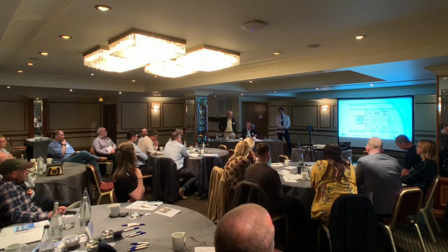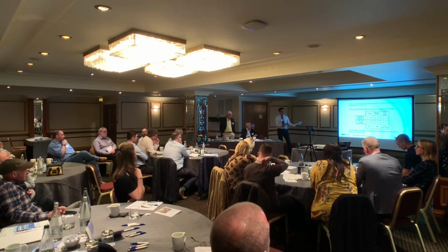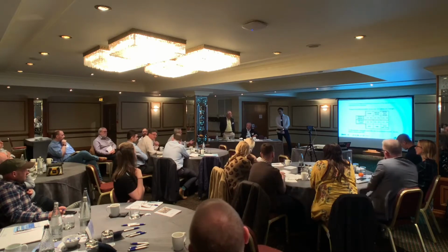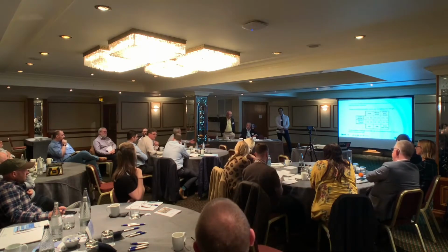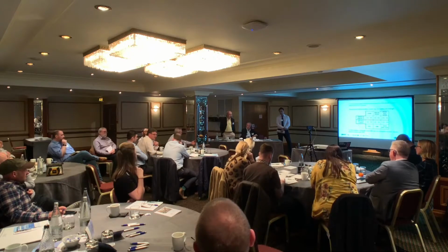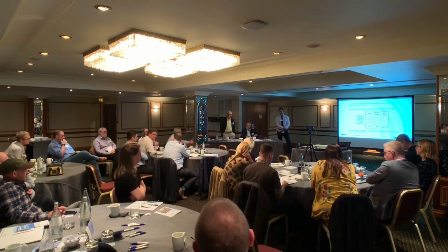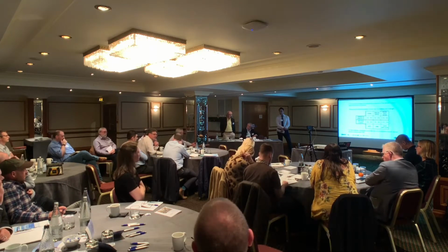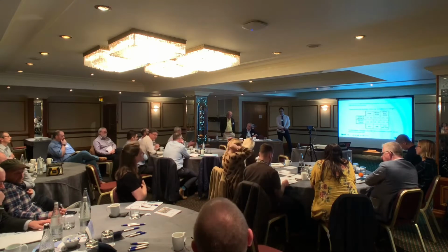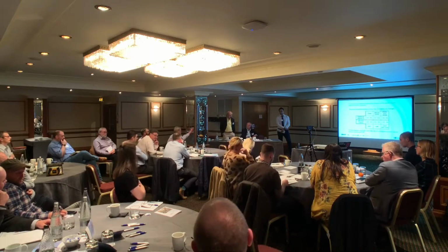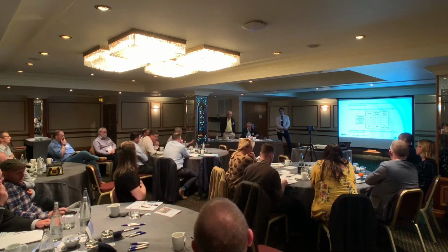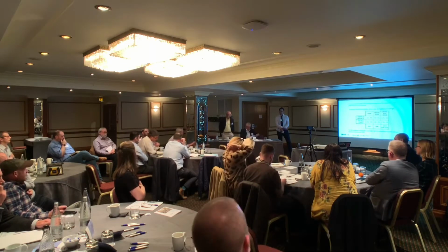Yes, it would go back to being conservative. You would do conservative damage risk assessments of any structure or service that you might be crossing. If that showed there's a risk of damage to that service, then you consider the cost of that damage and its repair, and you would appropriately move your tunnel or your crossing to suit that constraint.